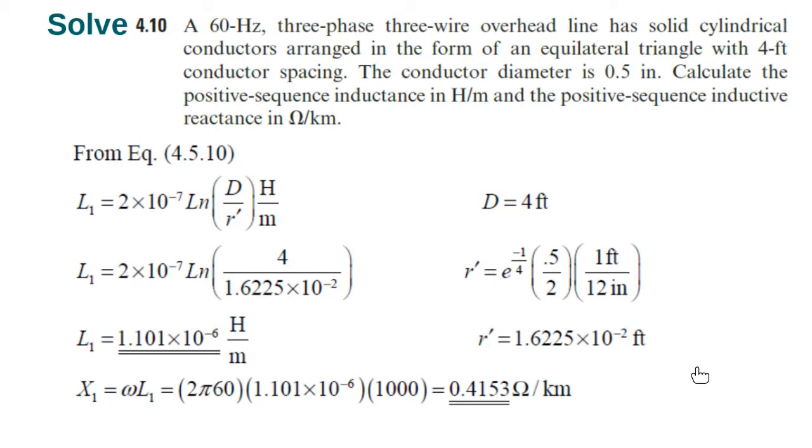And that's what they write, by the way, on the conductor: per kilometer or per mile. They give you per mile, or they give you per kilometer. The resistance, as you saw, is given per mile. The distance, they usually give in feet, not per mile, because the distance between the conductor and the conductor is close.